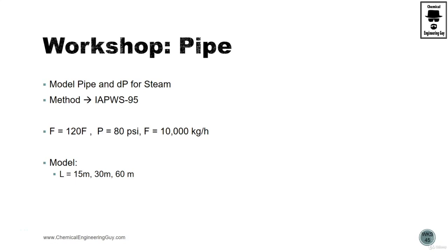So it's time now to model pipes, which are very important for flow rates and also to calculate pressure drops. This is very important, especially when we are changing flow rates, because when we change flow rates, we change velocities of the materials, and when we change velocity of the materials, the Reynolds number is changed, which directly implies that the friction is being changed. So essentially, if we change flow rates, we are changing friction factor or overall pressure drop.